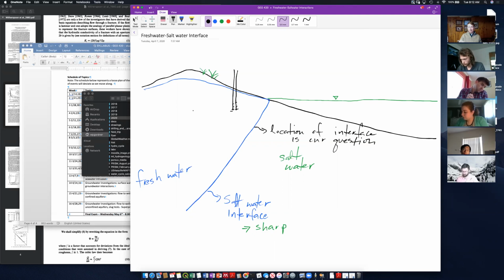The thickness of the freshwater unit, if we've only got a very shallow groundwater circulation system, then the saltwater will probably extend farther inland. How much water we're pumping, all right? If we're intercepting that groundwater flow, then seawater can intrude landward.